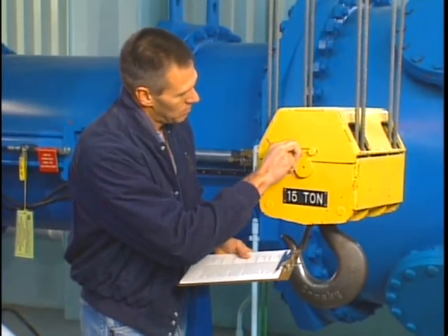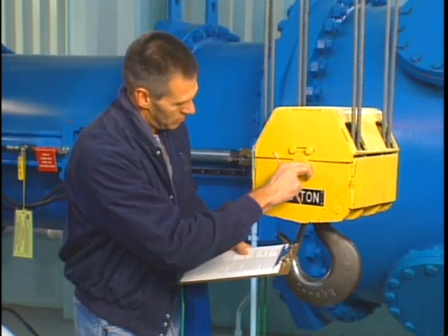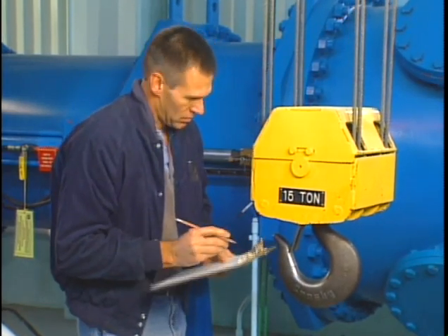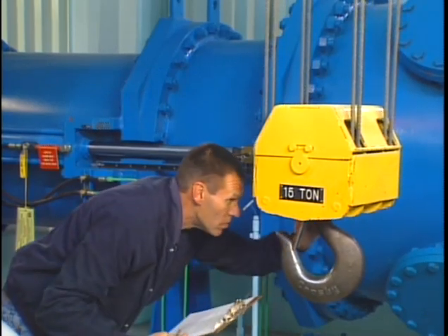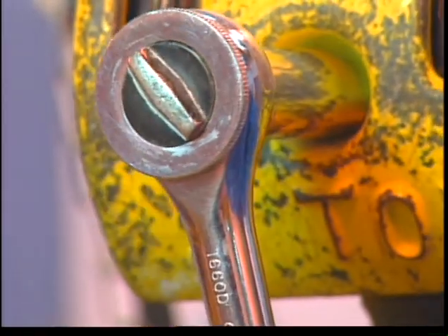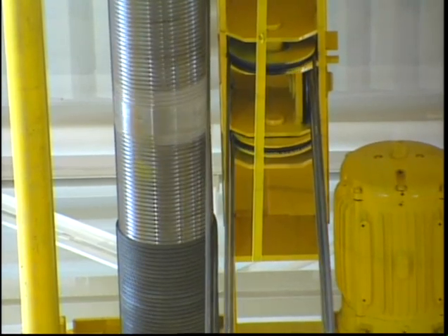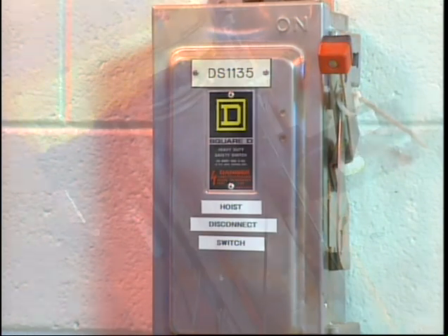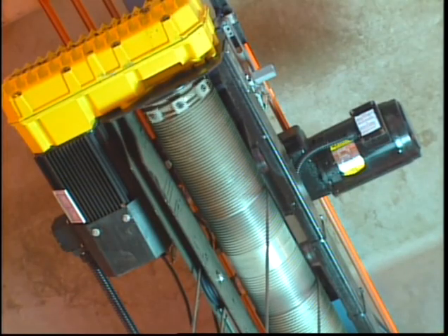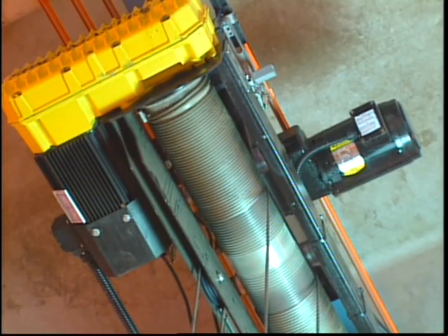For a periodic inspection, a qualified inspector should examine all of the parts mentioned earlier in the frequent inspection. The inspector should also look for loose rivets and bolts. The motor of the hoist should be examined. All electrical switches and components should be checked. Check the chain drive sprockets, bearings, gears, and rollers.